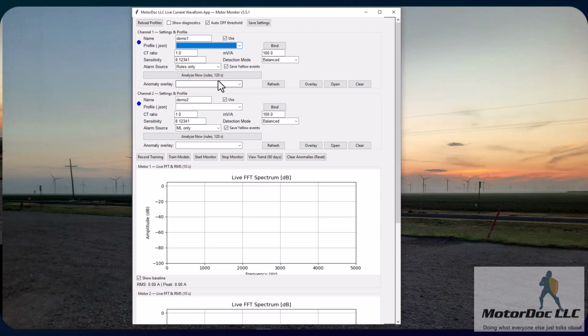The other thing it does, especially in the rules-based system, is auto-adjust for the noise floor. If I have variations in the noise floor, it will automatically adjust the alarms to accommodate. It will identify that I have a raised noise floor as an anomaly. However, as far as troubleshooting, green, yellow, red, etc., it is going to leave it there.